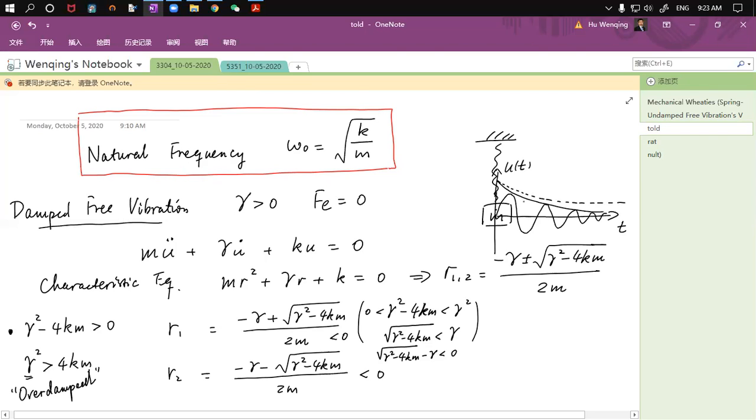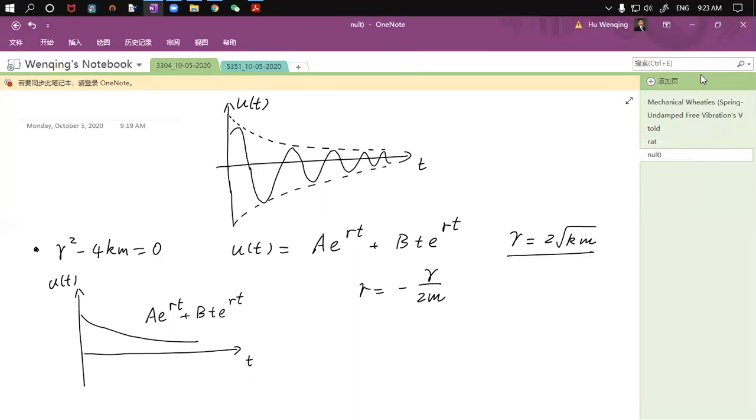If the damping is very large, then your system tends to do more exponential decay. If the damping is very small, the system tends to oscillate, right? So damping is fighting against oscillation, and in between you're going to have a trajectory that does not decay as fast as exponential, but still decays, right? So that's going to be your scenario.